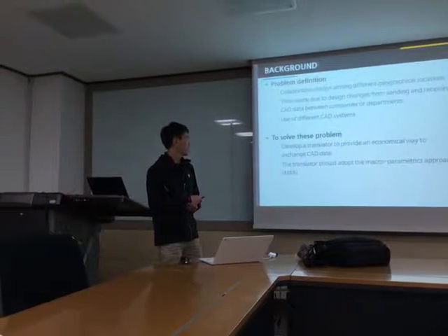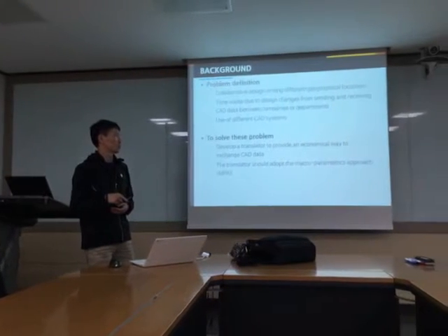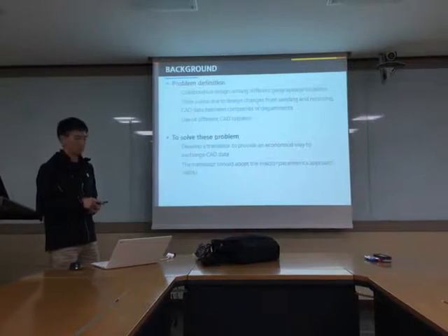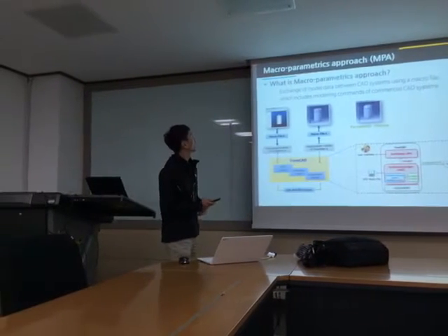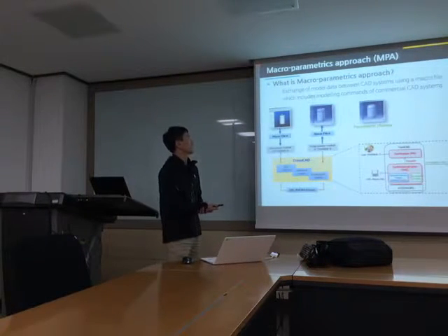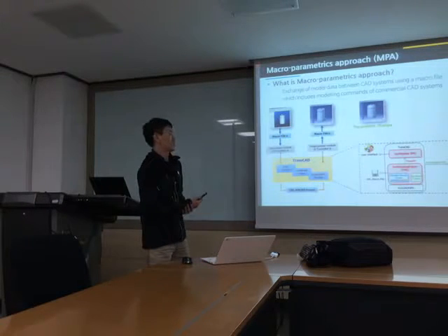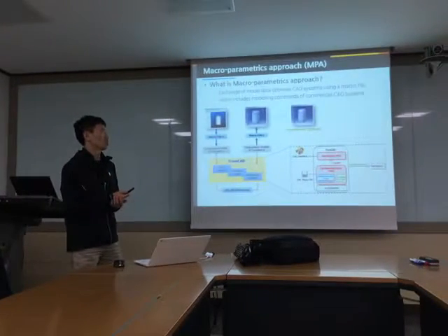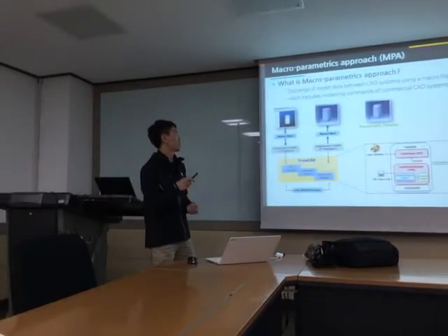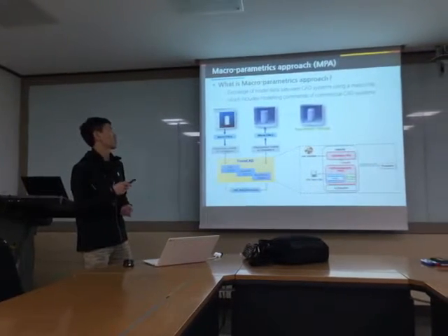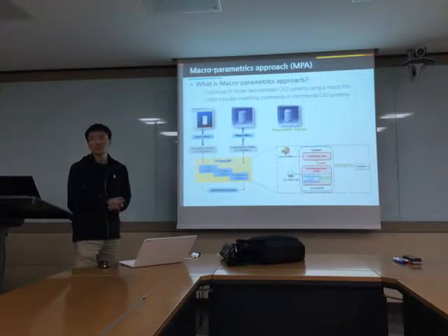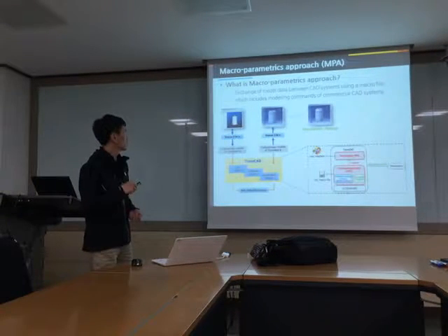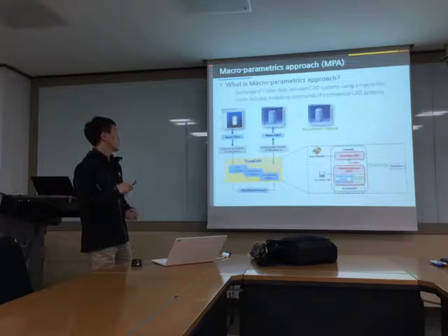And another thing is the translator should adopt the macroparametrics approach. I will explain this briefly. The macroparametrics approach is a methodology for the exchange of model data between CAD systems using a macro file. The macro file includes modeling commands of the commercial CAD system. So as you can see, CAD system alpha makes macro file alpha, and then we use the preprocessor.